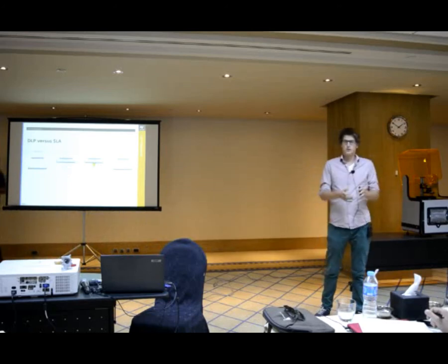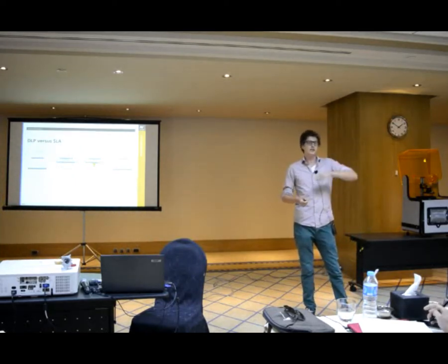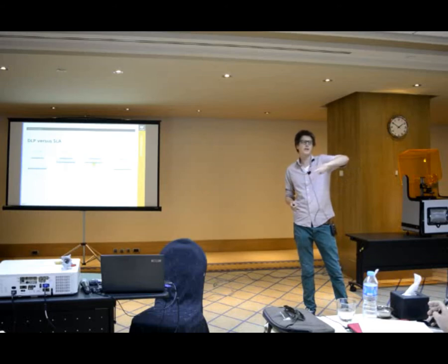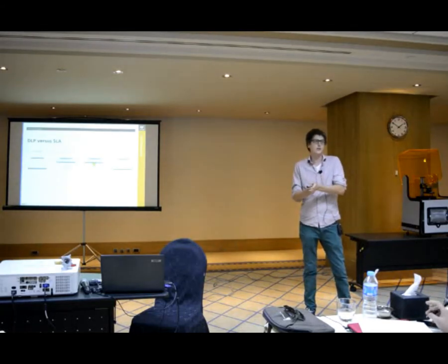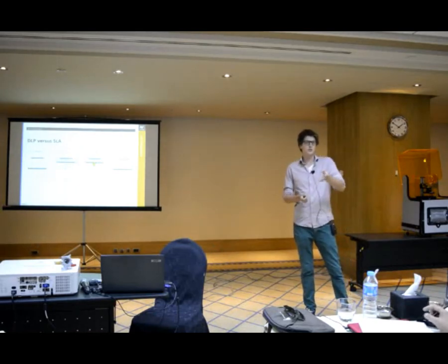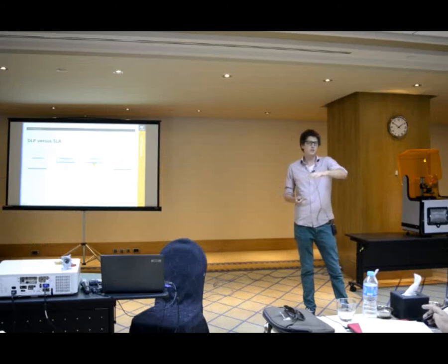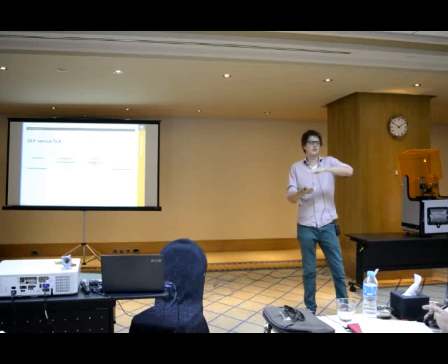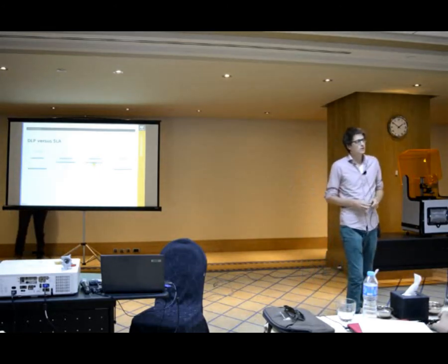For the differences, the SLA uses a laser, and this laser scans over the surface area, and where the resin liquid has to be cured, has to be hardened, it will shine light on those locations and it will not shine light on the other locations. And so by scanning over the surface, one can make a pattern in 2D. These patterns of 2D images are stacked upon each other, and together they will form a 3D image. So using a laser, we have to have a chromophore.